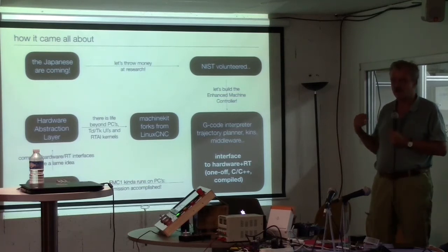Also, a fundamental limitation of Linux CNC is it is built on the assumption that everything has to run on a single shared memory CPU, on one machine. There is no middleware which allows distribution over remote user interfaces, for instance. And that brings its own set of problems. For instance, sometimes graphics hardware has some very specific version requirements on Linux support, and on the other hand, that collides with real-time behavior. So that is a constant source of problems.